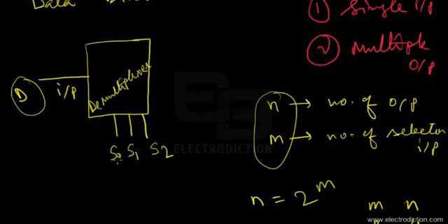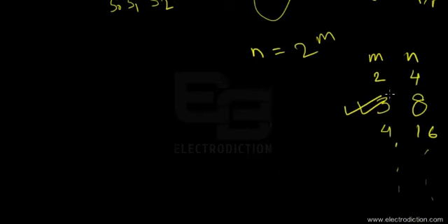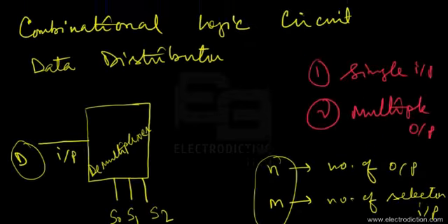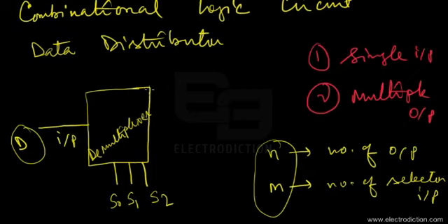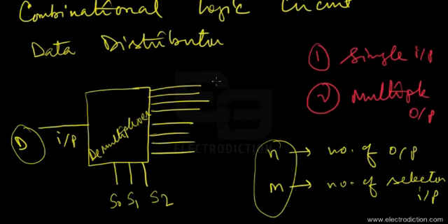So basically here, I'll just come back to the details later. Corresponding to 3 selector inputs, we would get 8 output lines. So I'll draw 8 output lines over here again: 1, 2, 3, 4, 5, 6, 7, and 8. I named them Y0, Y1, Y2, and so on. There is a little shortage of space, so fine, till Y7. In order to avoid cramming up the space, I did not name all of them.